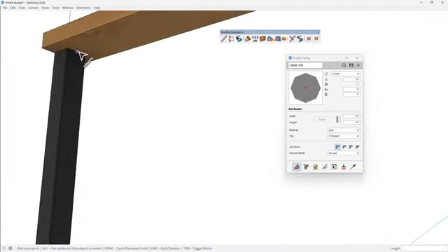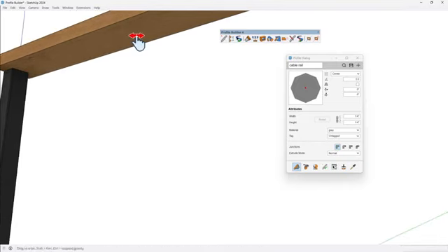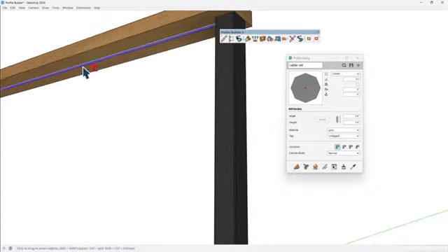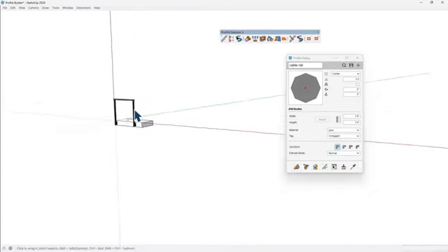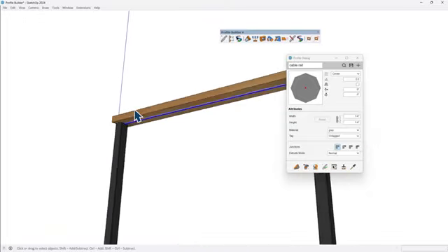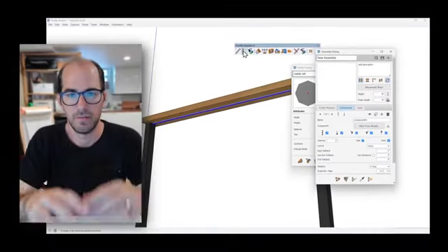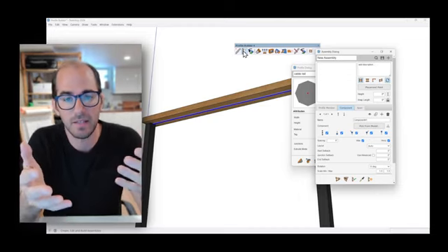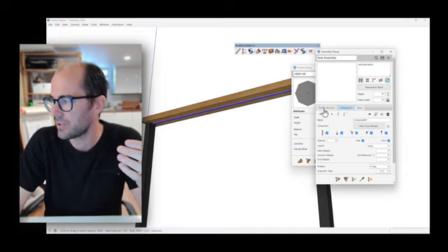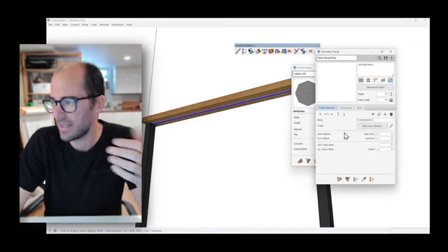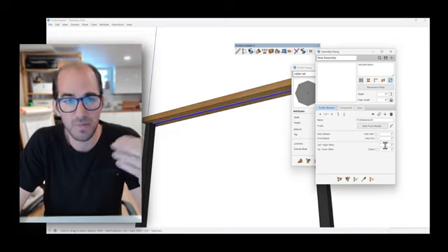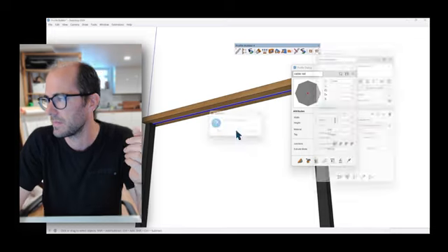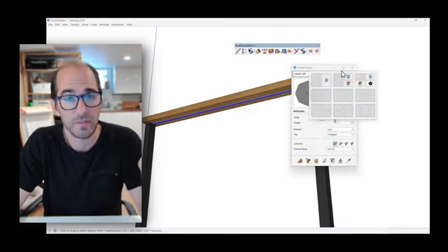So this time I'm going to go from the inside, from here, all the way across to here. I'll then take that, and this is where, let me zoom in a little bit closer. This is where building assemblies for me would take time, right? If I have cables, so there's like 8 or 10 of these that I need. And then I would have to make sure that I set each start and end position or the up and down offset. And I don't know the math and don't want to do the math. So let AutoAssembly do that for us.